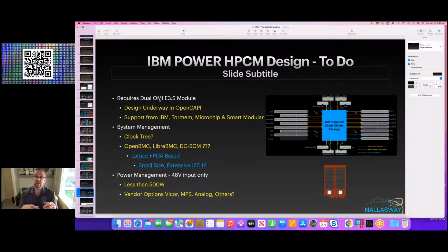And understand, yeah, IBM have their own proprietary bus called the symmetric multiprocessing bus, SMP, to connect. Because they've got those IOs on their device, we're wiring them to the connector. If I put an NVIDIA module down, there will be a lot of NVLink ones on these connectors. And I could potentially cable an IBM SMP to an NVIDIA NVLink, and it would be a disaster. It wouldn't work, obviously. But this part of our system management effort will be, to Todd's point, when we turn on, or before we turn on, the system management says, hang on a minute, you guys are trying to make an SMP bus talk to an NVLink bus.